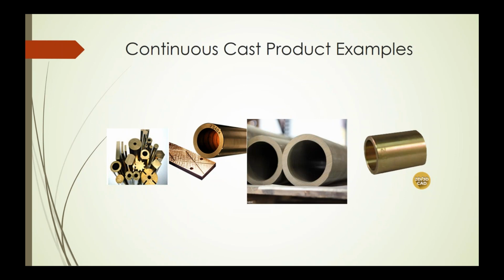To produce that on a continuous basis, and if it's aluminum bronze or bronze, it can be continuously cast in a variety of ways, but usually that's a tough thing to do. But if produced continuously, it is beneficial. You can cut it off to lengths, take those over and drill them, put whatever markings and or scores into it, finish the ends, things like that, and finish the product.